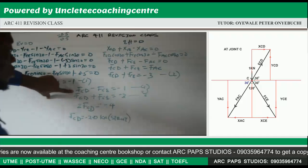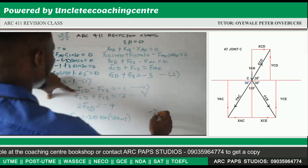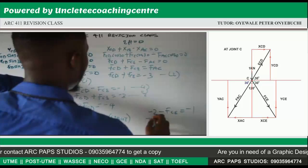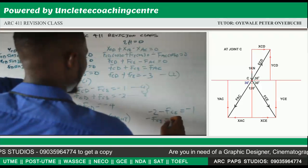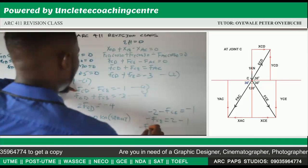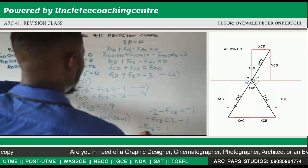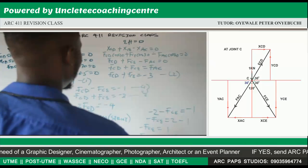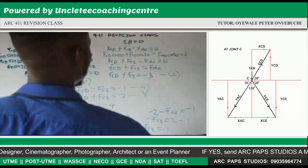If we are using equation 1, this will give us minus 2 minus FCE is equal to minus 1. So minus FCE will give us 2 minus 1. Minus FCE will give us 1. It means our FCE is minus 1.0 kilonewton, which is also a strut.